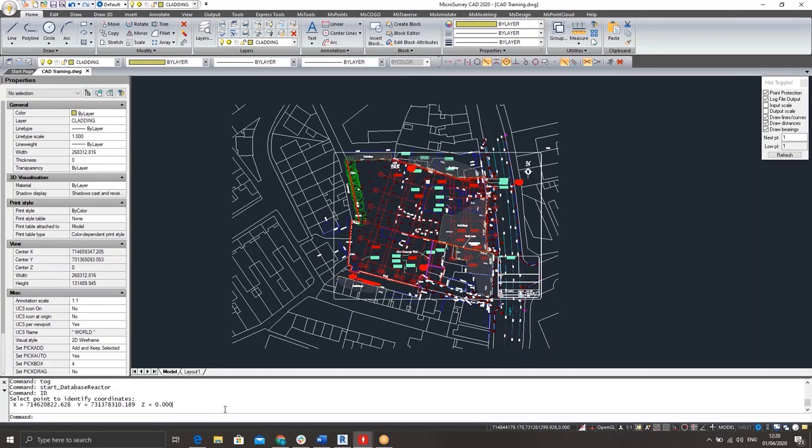So this is a good first step to have a good feel for things, especially if you're using GPS on site, because you will need to specify the coordinate reference system that you are using. If you have trouble understanding coordinate reference systems or you struggle to identify which one you are using, we will be putting up a further video where we go through coordinate reference system, a brief explanation, and also identifying which coordinate reference systems are used in Ireland today.